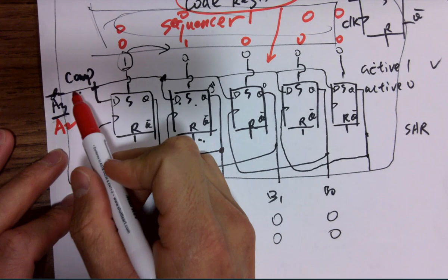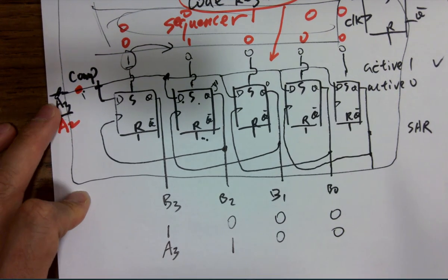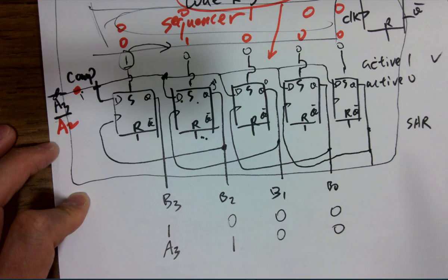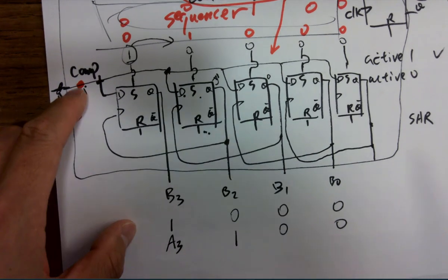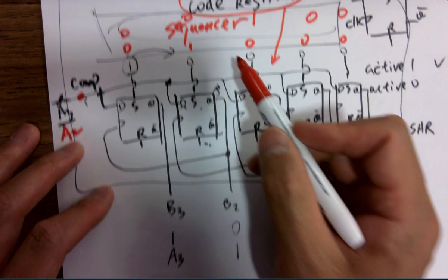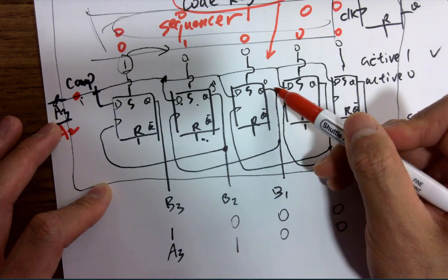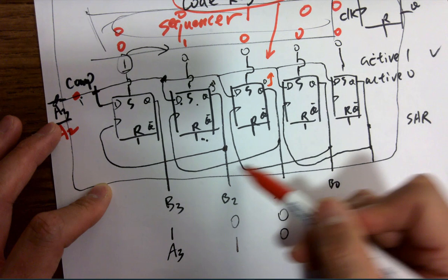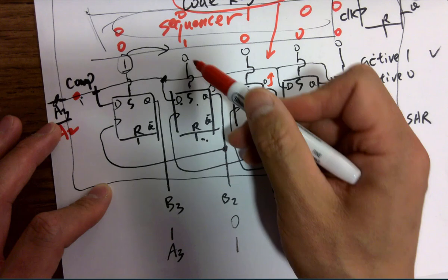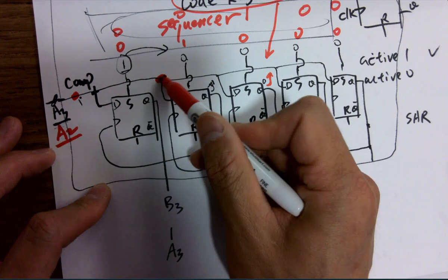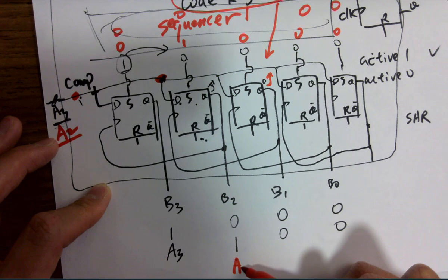So now at this line, it changes from A3 to A2. That's the second compared result. A2 now appears here, and then it's to the shift. So the shift will set this guy, and so this has a rising edge, right? So this one will trigger the clock here, and so this definitely will register whatever appears here, which is A2, right? Will be registered over here for sure.